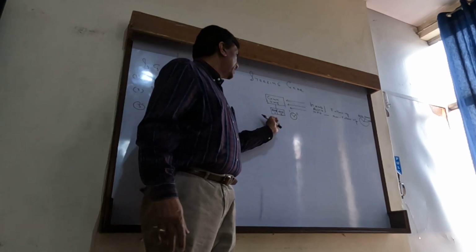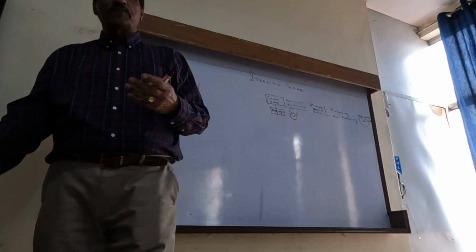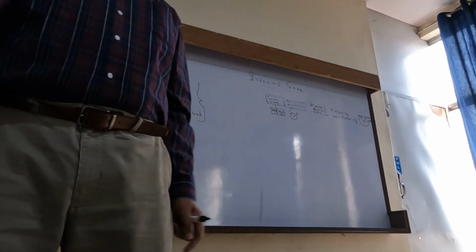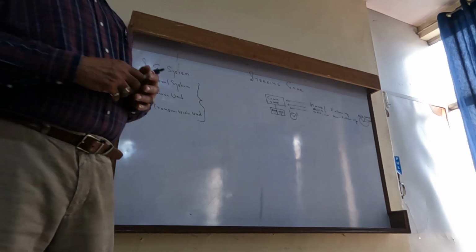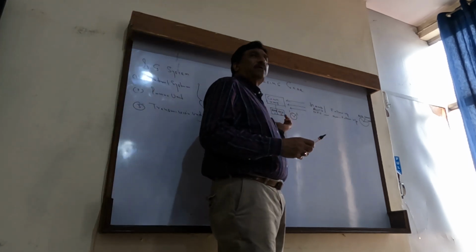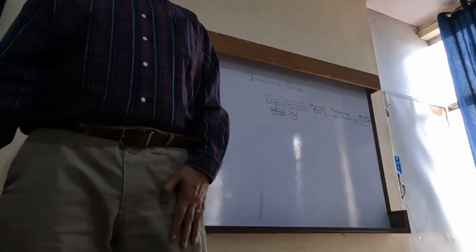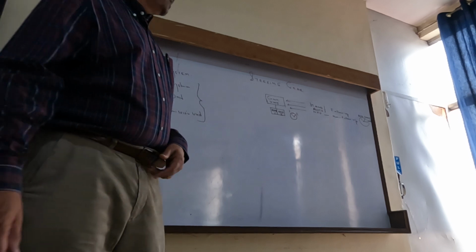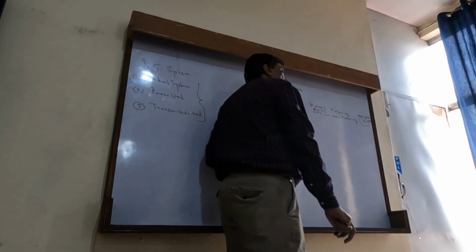Just to keep it in use, to be sure that both are working, we keep changing system 1, system 2. When we say system 1, it is a set of cards which are in action. This is standby. If I change to 2 also, same function. So 100% backup of these 2 systems. That is why we have a selection here, system 1, system 2.